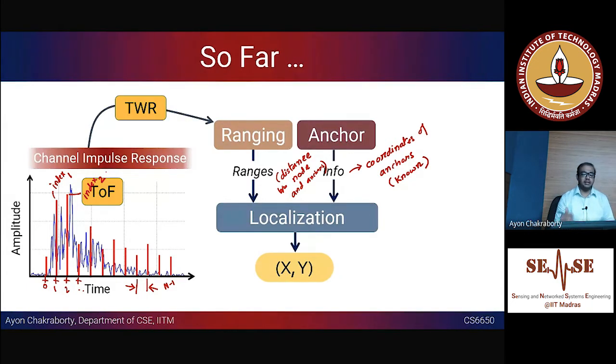Just the range might not be sufficient in that way, because there will be clock drifts and all. So what we need is a process known as two-way ranging, and in particular, we looked at a protocol known as symmetric two-way ranging in order to calculate the distance between the node and the anchors. Okay, and this calibration information is necessary because we had a discussion last day where somebody was asking about the location of the anchors being known, right?